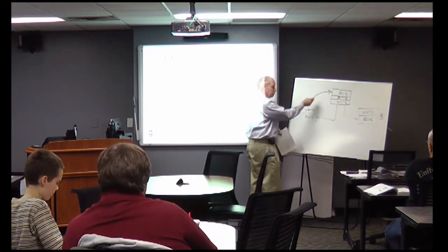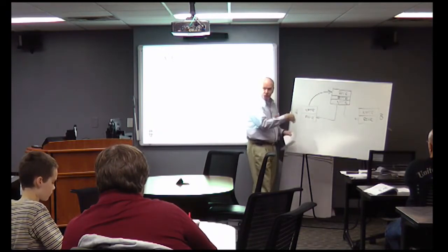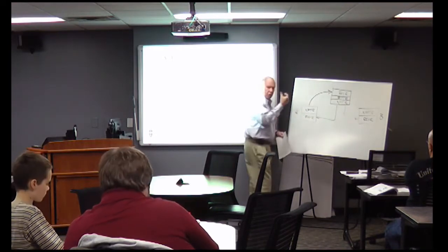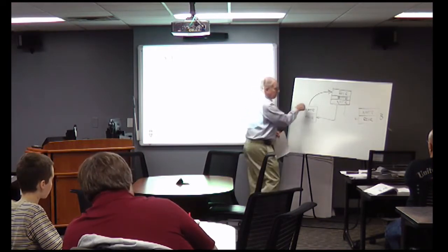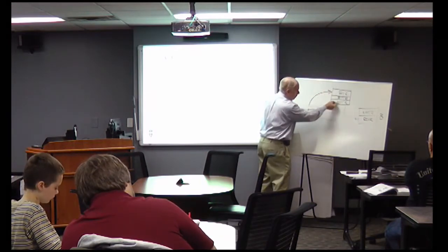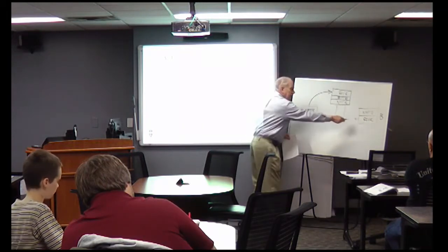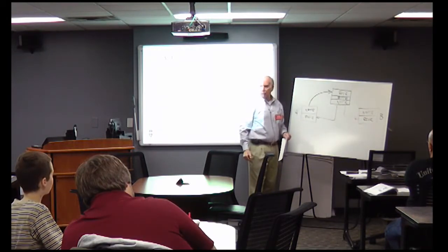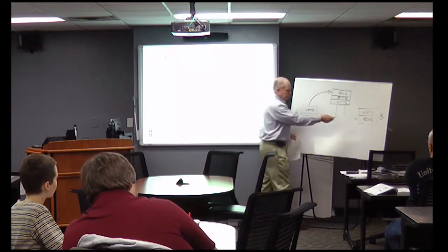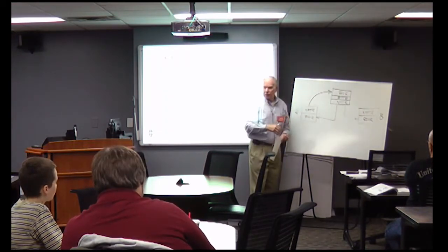But as long as I'm transmitting, I can't hear this. In other words, my station can't transmit and receive at the same time. So I push the microphone, I start talking, the radio transmits, the repeater hears it and retransmits it out, and the guy over here can hear me even though we may be 30 or 40 miles apart. And if station B wanted to talk to station A, you just reverse the process.